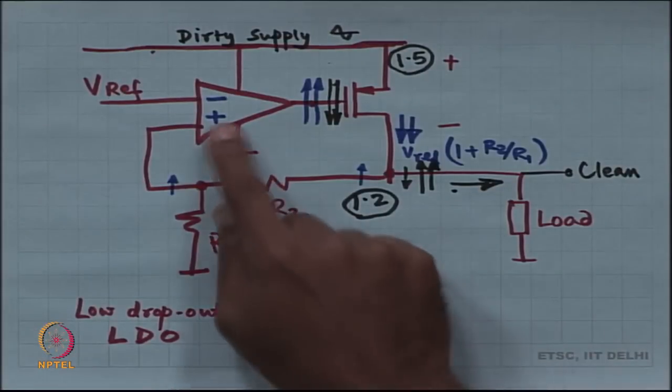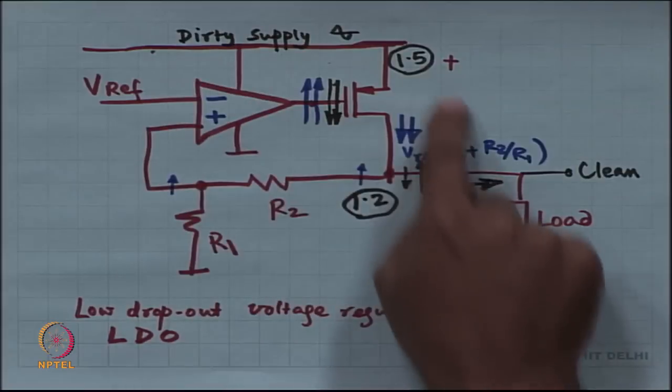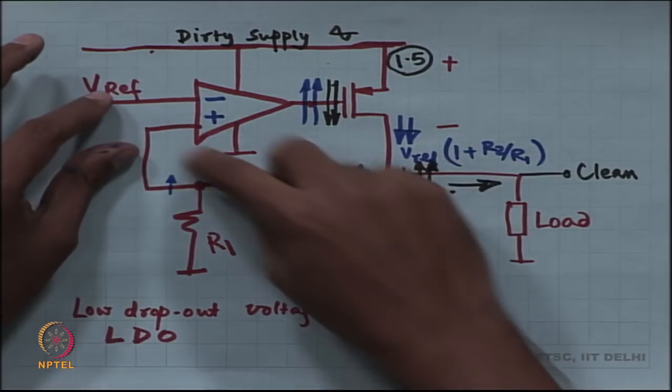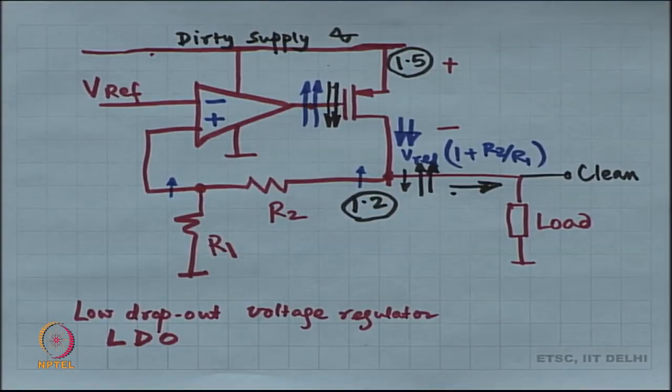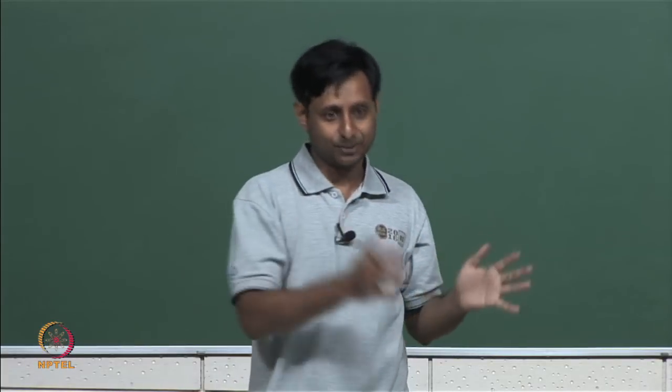However, over here if this is a 2-pole system, the net structure is actually 3 poles, right. It is as if you have got a 3-pole amplifier and then you are placing it in feedback, all right. Now, when you do that, you have to compensate the 3-pole amplifier and not the 2-pole.